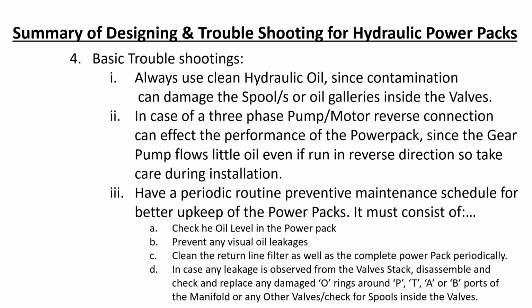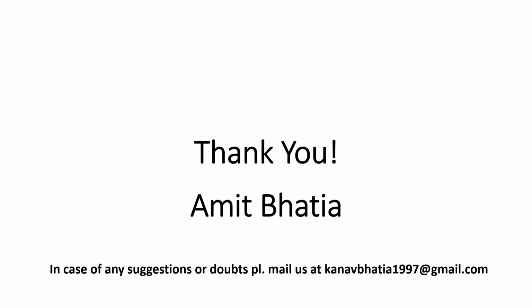Have a periodic routine preventive maintenance schedule for better upkeep of the power packs. It must consist of checking the oil level in the power pack, preventing any visual oil leakages, and cleaning the return line filter as well as the complete power pack periodically. In case, check and replace any damaged O-rings around the P, T, A and B ports of the manifold or any other valves, or check the spools inside the valves.